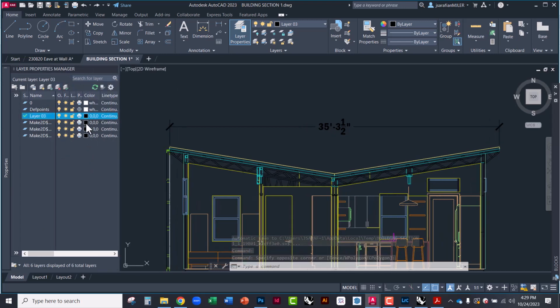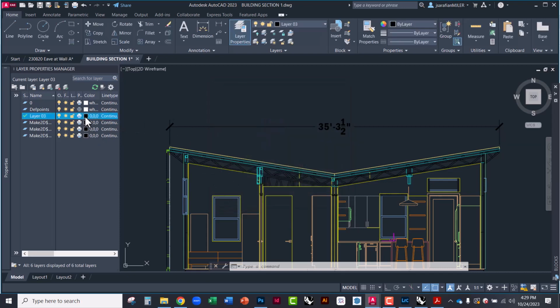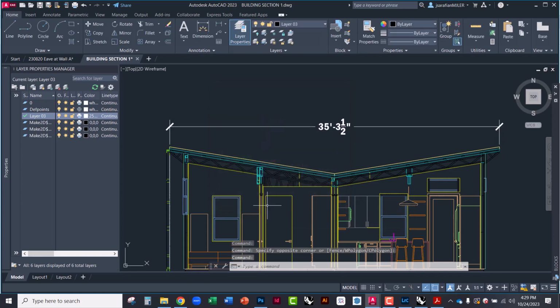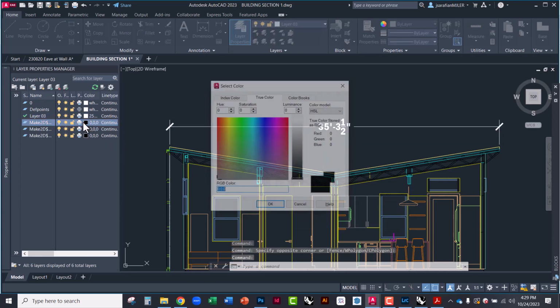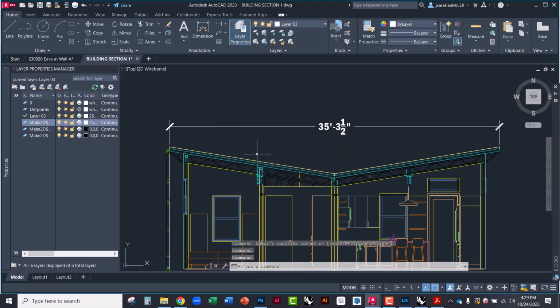Often in Rhino, a lot of these layers that show up as black line weight show up in black in AutoCAD, which you really want those to be white, so that when it prints, it shows up. Either way, it'll print as black, but we want to set this to be white. And so you can go in and change the colors of different layers here.